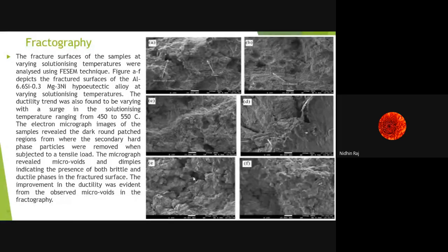Now, the decreasing trend is observed with the increase in the solutionizing temperature after 510 degrees Celsius. And this trend was actually attributed to the reduction in precipitate volume and the number of vacancies in the alloys. And this was actually reported by a previous literature paper also.